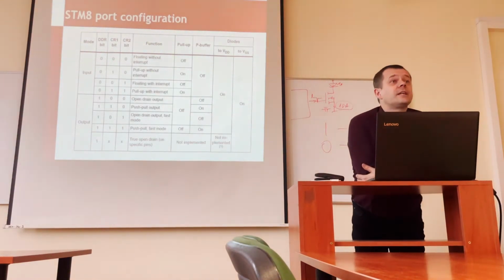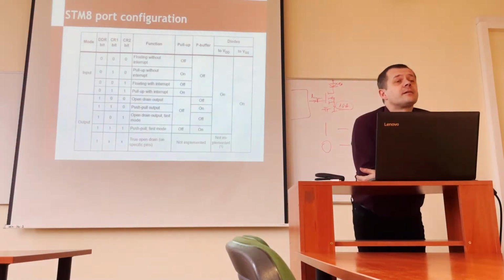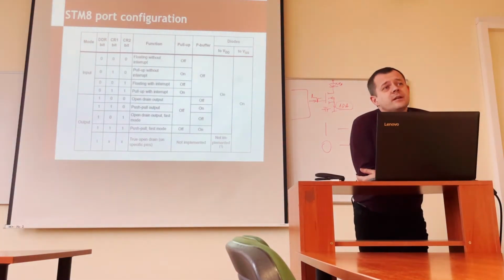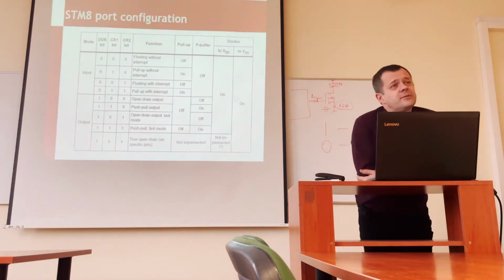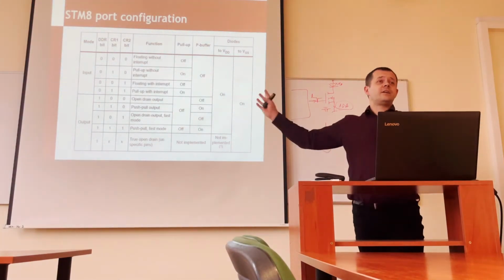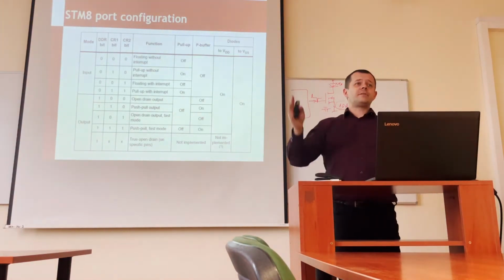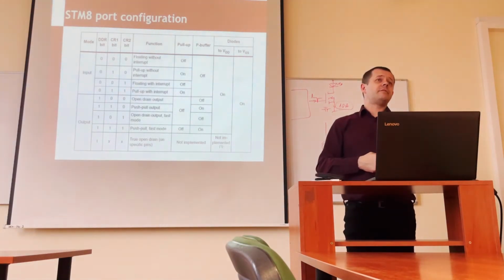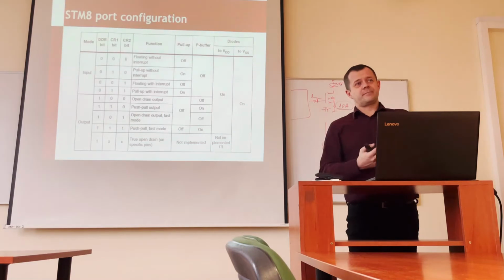That's not standard, yeah? So is there an interrupt vector for every pin or for port? For port. Okay. That's for port. So it's again different for different microcontrollers. It's done in a different way in case of external interrupts, because sometimes there must be some aggregation, there are too many pins.